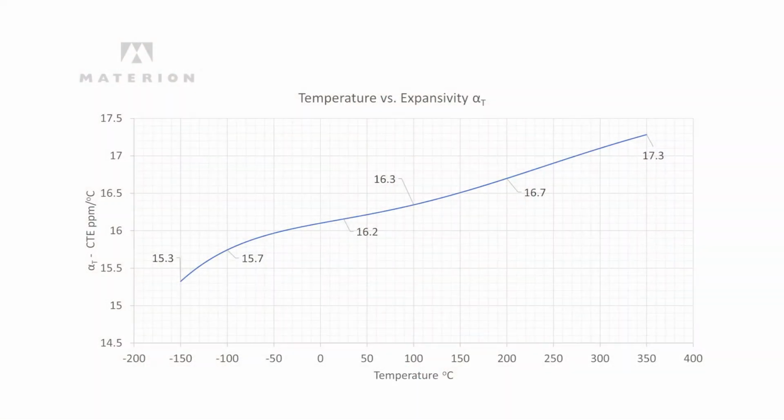The focus here is linear coefficient of thermal expansion, but note that the area and volume will also undergo thermal expansion because thermal strain expands in all three directions. CTE values are many times displayed as a single value, but the CTE is a function of temperature. CTE data can be presented as a table with average CTE values over a temperature range, or it can be presented as a curve showing the instantaneous values, also called alpha values, over a temperature range.